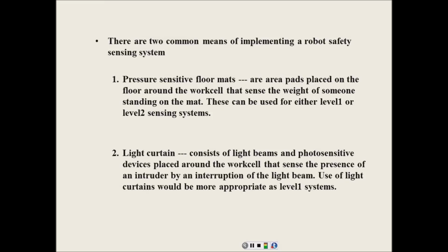And if you walk through that curtain, then it's going to detect you. And what's nice about that is that if we've got carts or rails coming in on a slide that need to come through the light curtain, when it gets up to it, you can disable the portion that that thing occupies and move it in and drop it off. So these things are pretty popular.